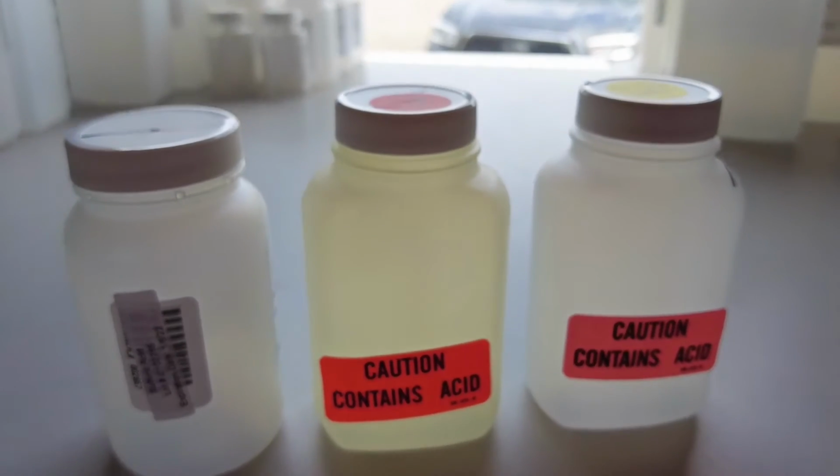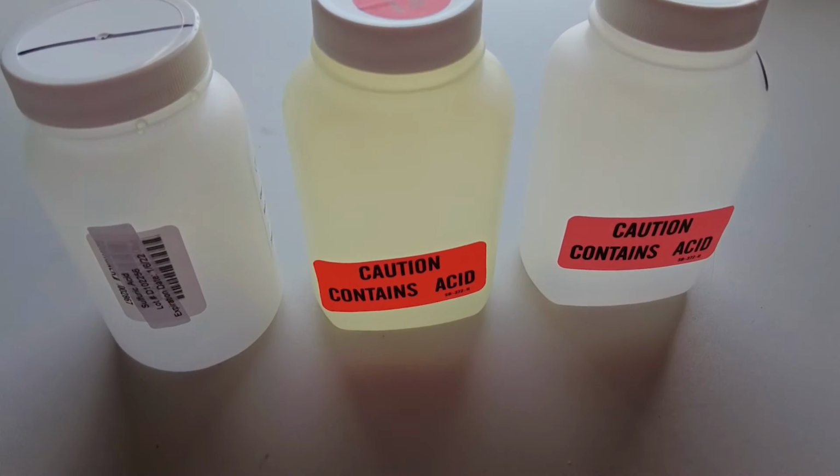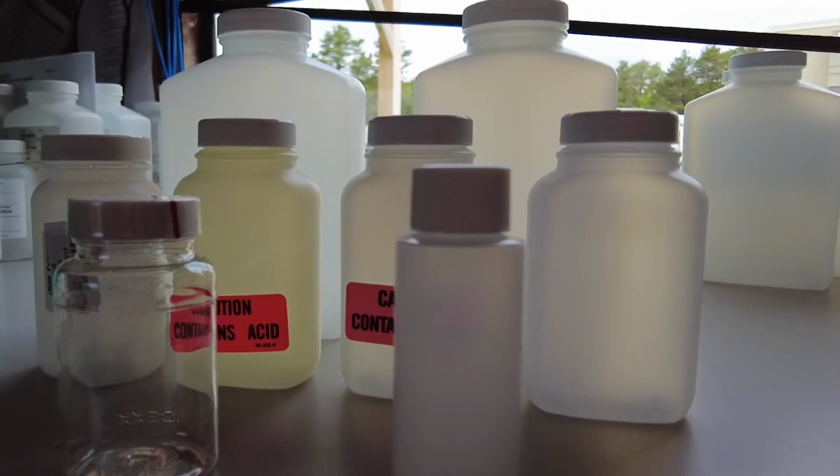For field sampling, it's essential that you treat the sample properly. If you take a sample, certainly most of them have to be on ice. Some of them need to be preserved. So your TKN and ammonia samples have to be preserved, so they should be in preserved bottles. And you can't keep those bottles in the hot sun in your back seat while you're waiting to take the sample. Each one will have a drop of sulfuric acid in it, or if you're doing other things, might have hydrochloric acid in it. And you want to make sure that those are fresh bottles from the laboratory. Then after you take the samples, keep them on ice.